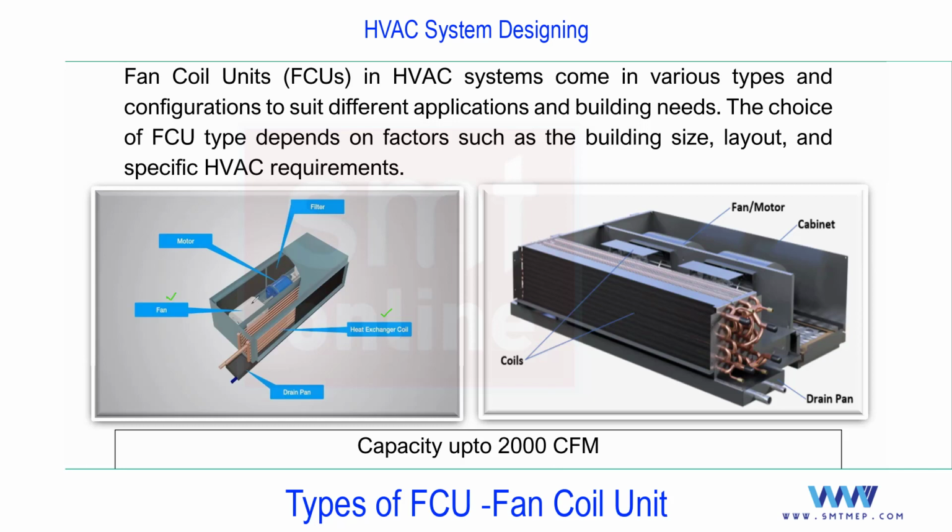Next, the fan. There's a fan casing, and inside you'll find the fan motor. It can be one casing with one fan motor, or two fan motors, depending on the capacity, the configuration and the make. You'll find the fan motor and the filters. And here is a cooling coil with a bunch of fins. These are the two fan blowers, and in between you'll find the motor with two shafts.